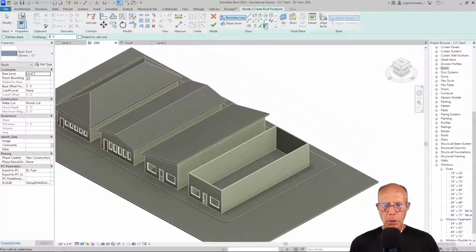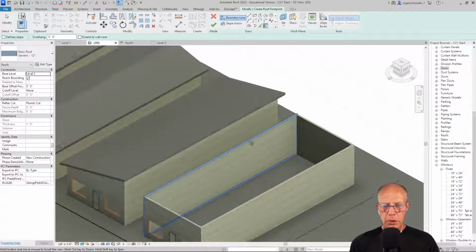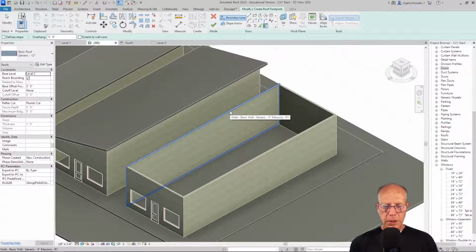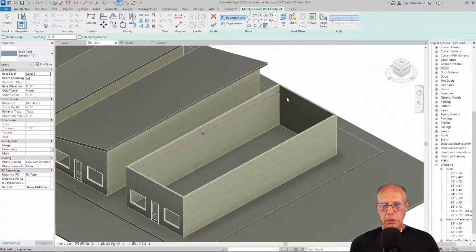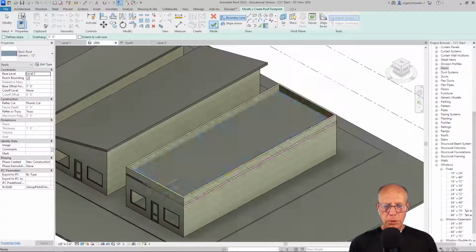So we're going to use our pick wall tool again. And you'll notice when we come in here, and I'll zoom in, you notice how it's showing it going down a little bit. That's that 4 foot offset. Our wall is 4 foot higher than our actual roof is going to be constructed. So I'll just go ahead and click on these and select them. And I think it is extending it out to the exterior boundary of the wall. And we'll see what that looks like.